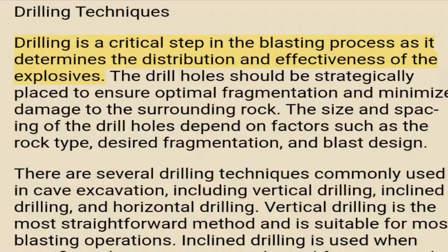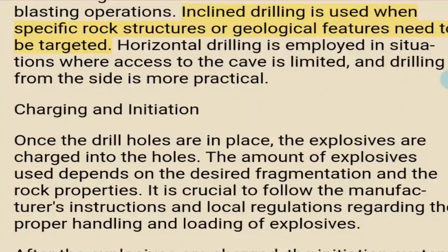Drilling techniques. Drilling is a critical step in the blasting process as it determines the distribution and effectiveness of the explosives. The drill holes should be strategically placed to ensure optimal fragmentation and minimize damage to the surrounding rock. The size and spacing of the drill holes depend on factors such as the rock type, desired fragmentation, and blast design. There are several drilling techniques commonly used in cave excavation, including vertical drilling, inclined drilling, and horizontal drilling. Vertical drilling is the most straightforward method and is suitable for most blasting operations. Inclined drilling is used when specific rock structures or geological features need to be targeted. Horizontal drilling is employed in situations where access to the cave is limited, and drilling from the side is more practical.